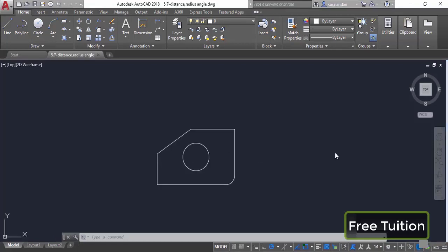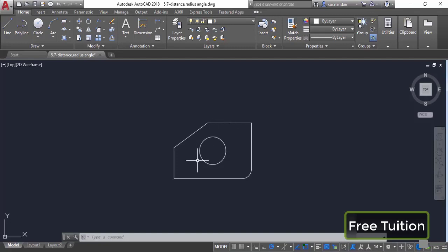In this video I will tell you about finding distance, radius, angle and coordinates from the simple AutoCAD geometries. And for that I will use this simple 2D drawing. Here in this drawing we have the circle, arc, simple lines and also the slant line, and we will find different properties of this geometry using the inquiry commands.